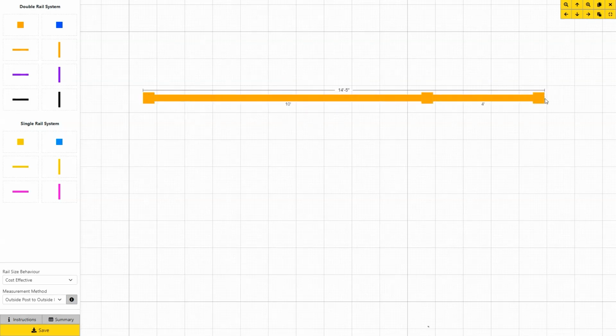So here, it's created a 10-foot rail with the maximum size and another 4-foot rail. I'll stick with the original configuration though, where I've got a 10-foot rail. Now keep in mind, the rail just can't hang in midair. It needs a post to support it. So when the rail is in this candy striping color, it means it's not configured properly. So when I click on the rail again, I can do two things. I can hit this plus sign and it automatically adds a post, changes the color to the standard color for that object, and now it's completely configured. The other way to do it is to drag the post of my choice on, and that also configures it.